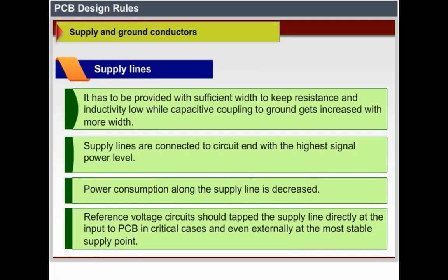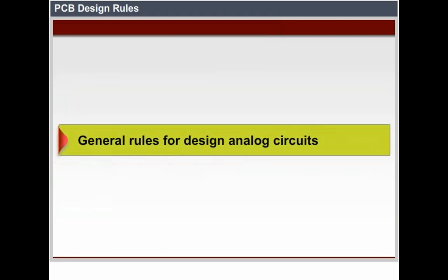Reference voltage circuits should be tapped from the supply line directly at the input to the PCB in critical cases, and even externally at the most stable supply point. General rules for design of analog circuits.